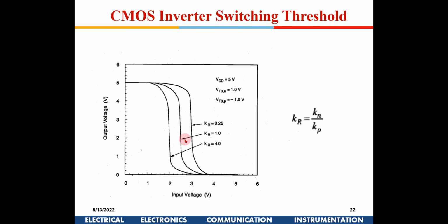Yes. Okay. So for example, if I keep this 400 nanometer and 1000 nanometer PMOS width, length being 180 for both, I will get this curve. Now if I increase the value of N, or I decrease the value of P, either way I will move towards the left. And I will move towards the right if I decrease the value of N or increase the value of P. Is it okay? Yes. Okay.